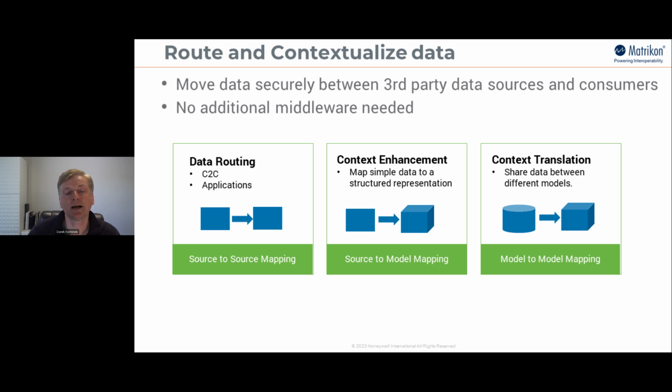Okay. Now, the other thing about being able to bring in the modeling is that you also need to be able to map it. And mapping has to do with how you create a structure, but now you have to attach the real world data to that structure when you instantiate to say, okay, now I've got a conveyor belt system, like we said. So conveyor belt system 1, I want that to talk to specific PLCs on that particular line, or whatever sensors you've got. So you have to be able to map the physical data that's coming in or the protocols to specific items in your model. So you either do that just to facilitate controller to controller communications, so one PLC doesn't talk to another, this acts as kind of a bridge between them.